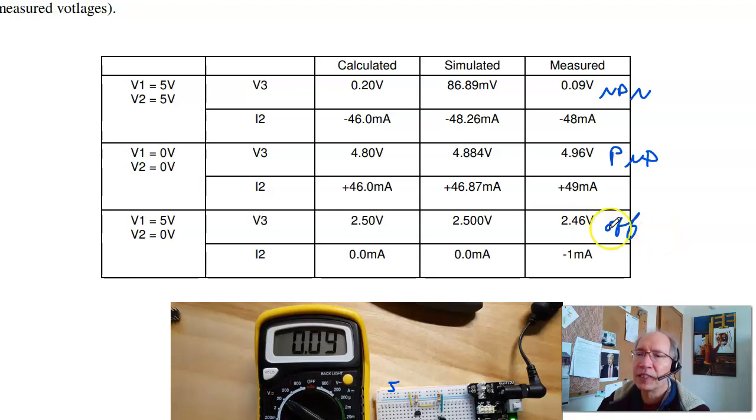So that's an H-bridge. And typical in this class, I've got the same circuit with 3 different answers. I've got what I calculated, what I simulated, what I measured. They're all different. They're close, they're consistent, but different. That's just because when you calculate, we're using an ideal diode model. Diodes aren't ideal. Simulated uses a more accurate model. That's still just a model, slightly inaccurate. The acid test is what does it really do? CircuitLab is closer than the ideal diode model. This is really what you want.